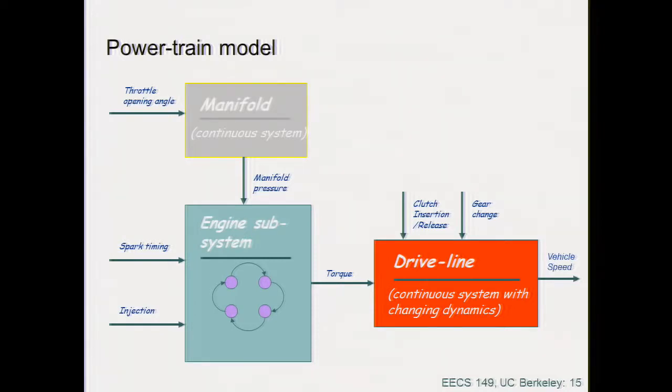Each phase is characterized by the fact that the piston reaches its topmost position. It's called dead center. So a piston goes up, changes phase, goes down, changes phase, goes up, changes phase, goes down. So 4 states. For each cylinder, there are 4 states, which correspond to: I'm going up, I'm going down, I'm pushing away the bad stuff, I'm taking in the good stuff. 4 states. So I can use a finite state machine. Now, what is the trigger that tells me when I need to change the state, right?